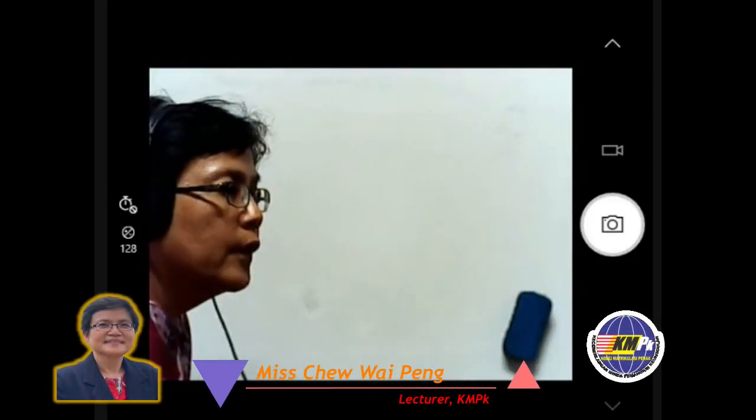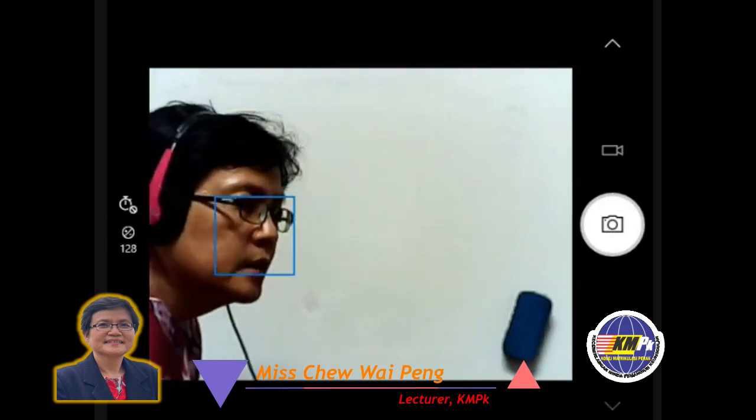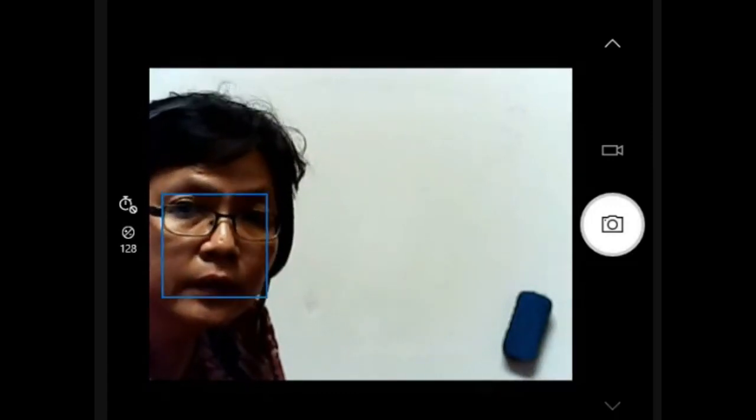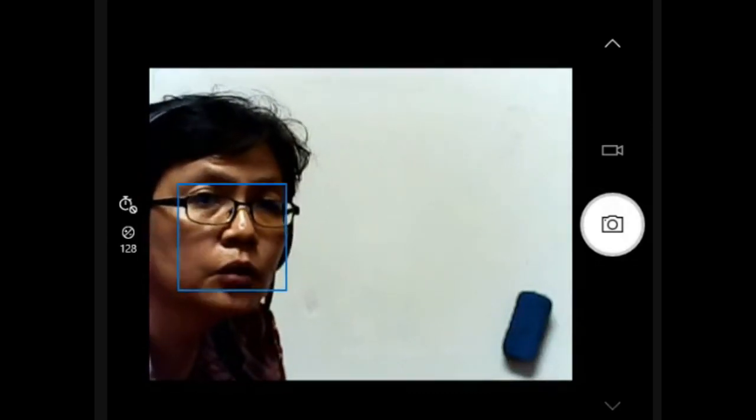What you really need to know is that for a pure resistor, the voltage across the resistor is in phase with the current. Very important. In phase meaning the angle is 0 degrees. Then for a pure capacitor, the phase angle is 90 degrees, or the voltage across the capacitor lags the current by 90 degrees. For a pure inductor, the voltage across the inductor leads the current by 90 degrees. These are the concepts that you need to know.